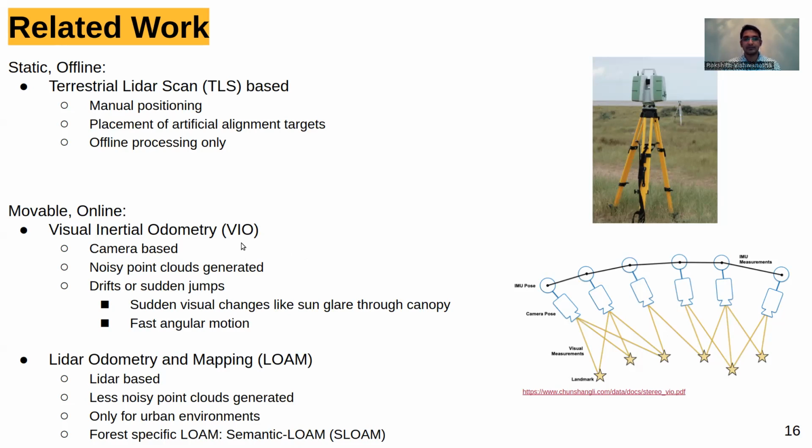But from a performance standpoint, in terms of an application standpoint, I think the main benefit between using LiDAR and visual odometry would be that you don't have to depend on light in order to map. If you had to go into a really dense forest where a lot of light changes would happen, because of breaks and openings in the canopy, or depending on the orientation of the drone, if you were trying to look upward a little bit, glare from the sun would also add to drift.